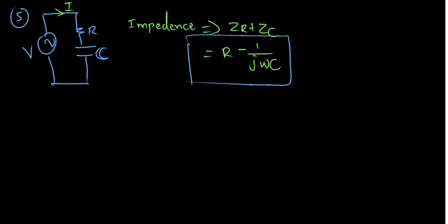How to draw the phasor diagram? I already told you we start from the common one, which is the current I. The next, VR, is not leading or lagging the current, so VR is placed here. I take I greater than VR. If your value of I is less than VR, then VR is beyond, like here.